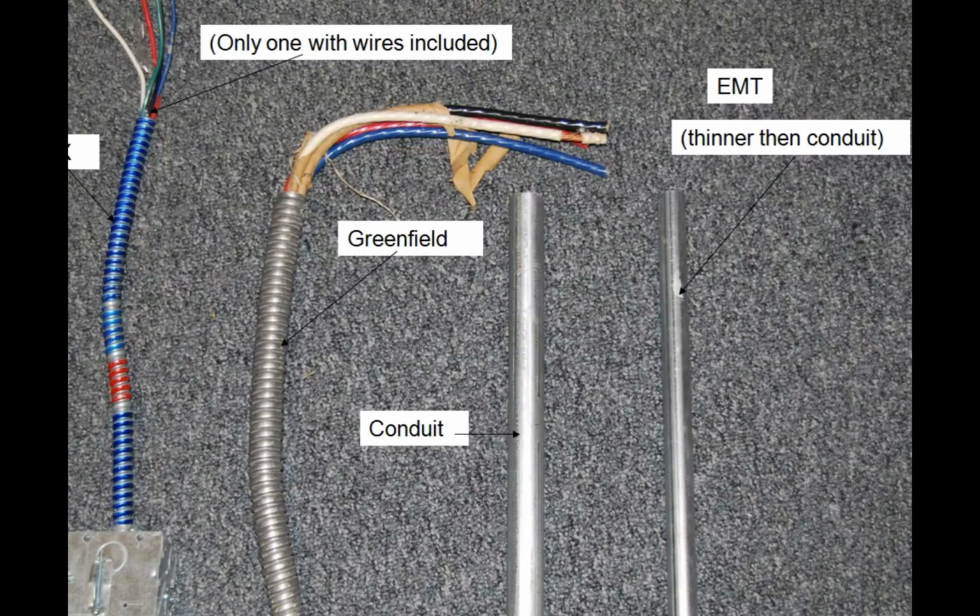Alright, so you can see some of the armored cables to the left. It has that metallic look, it's ribbed, it has wiring running through it. BX is the one to the left, and that's one of the more typical to be run through buildings. It carries your three-phase conductors plus your neutral, and it's sold as a complete set. When you buy BX cable, it'll have the 3 phases, probably number 12 wires in there with the neutral, and you basically connect that from point to point and you're done.